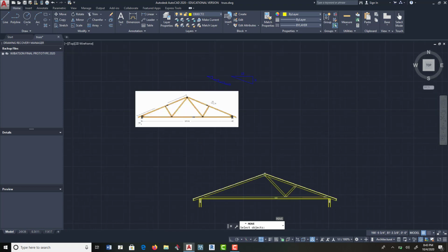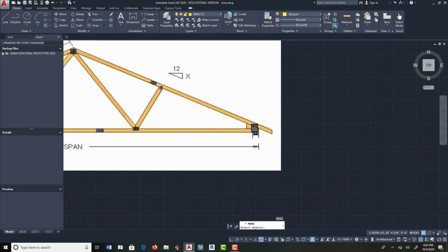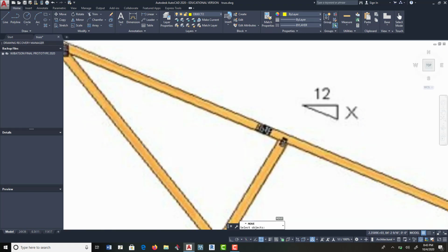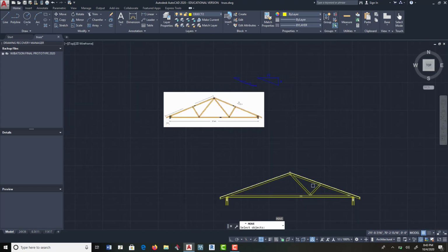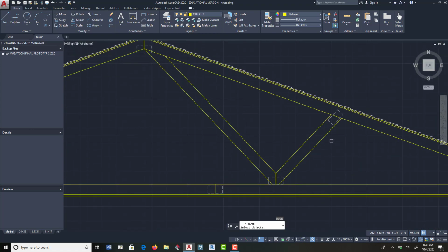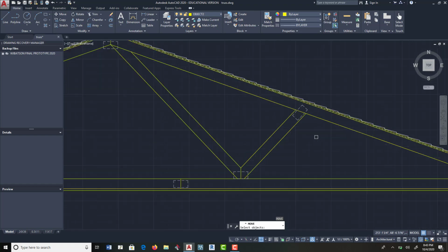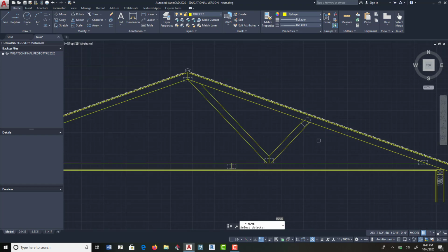Okay, good. So now you see you've got that one, you've got that one, you've got that one, and then sometimes these members they're too short, so there's a piece right there. So we'll leave those off, okay? Because this is only a 24-inch truss. Well, we've got the overhang there, so if you want to, you can put that piece up there. But they're really not necessary. And typically, when you're doing a working drawing for residential architects, they don't demand that you do that. I had only one boss that made me do it, because the trusses will already be purchased with those on there, so you don't have to draw them. You really just have to label what truss size you have.